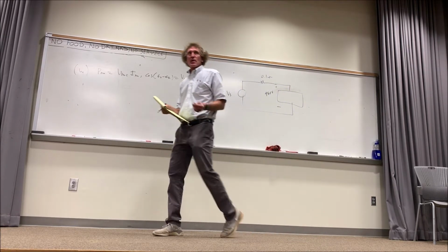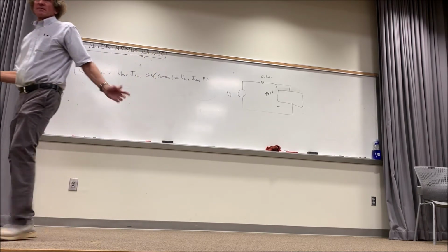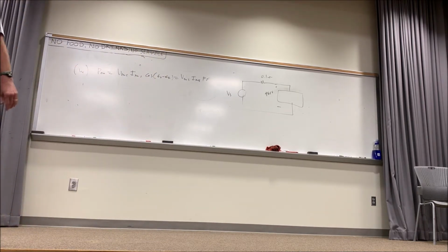In the United States, you're probably used to seeing the wall is 117 or 120, depending on how you read it. It's really 117 RMS. That's RMS voltage. And you will see the next thing you're going to get is a plus and minus that are 240 volts. If you have a dryer, anybody know what I'm talking about here? That's going to be a plus to minus, and then a minus to plus, but it's the same phase, and I'll get to that later.